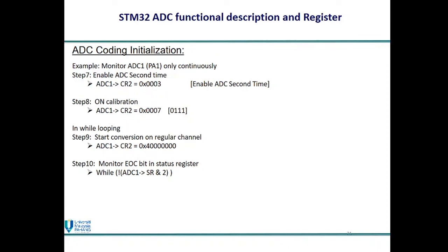The last step is to monitor the status register of the ADC. There is bit 1, the EOC flag. We need to monitor this bit to make sure the conversion is complete.